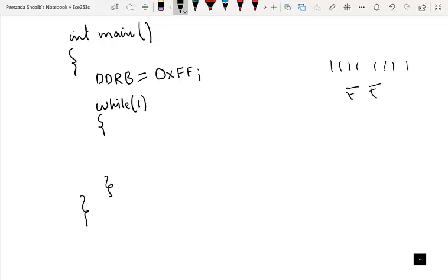So what I can do is write PORTB. I will turn on the LEDs by sending ones to each pin. That means I will write 0xFF. Then I have to write some statements which will cause delay. We are not discussing those statements yet because there are a couple of ways, more than two ways, to incorporate this delay in C programming. So let's keep it there for some time.